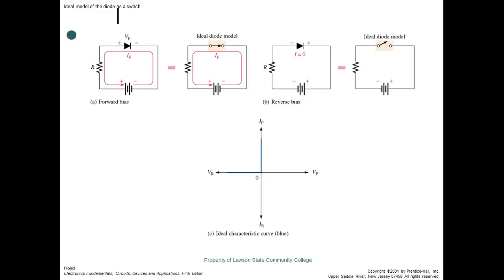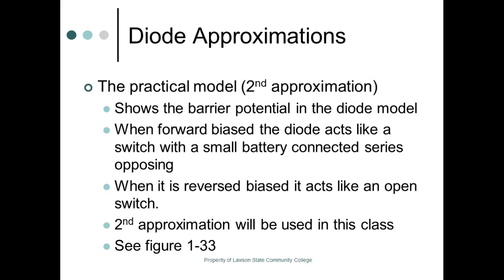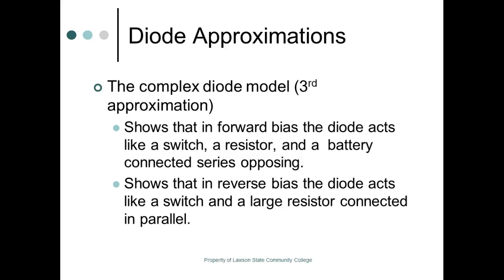Talking to my troubleshooting class. So y'all know what y'all did, right? You said always required no matter the voltage. That's not true. I see all these auto mechanics out there with all this PPE on. No, so it's not always required. Just above 50 volts, we got to start looking at personal protection equipment. Above 50 volts, PPE is required; below 50 volts, PPE is not required. Y'all understand that? Like now we do.